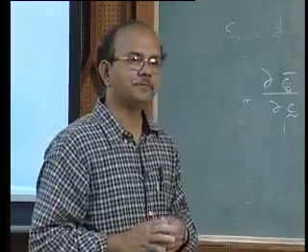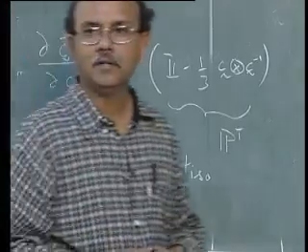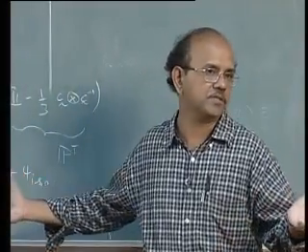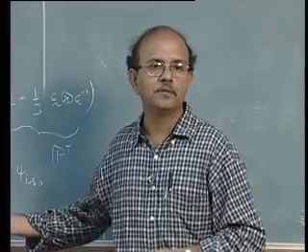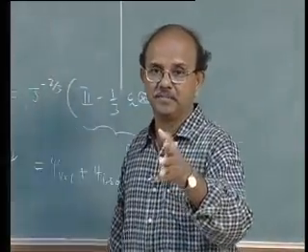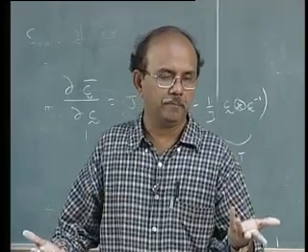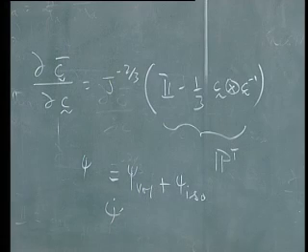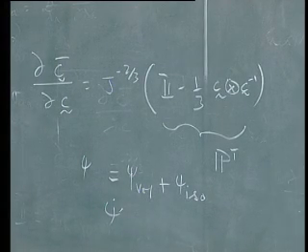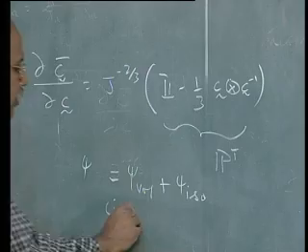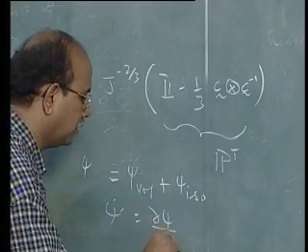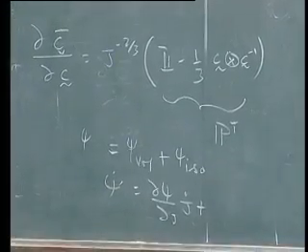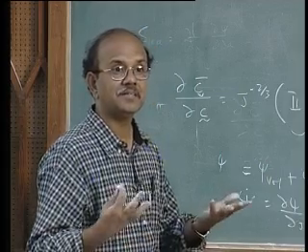Once I write like this, again see that we are going to use the old theory, what we know. What is it that I'm going to do now? Ultimately I want to develop a stress-strain relationship or stress-deformation relationship. All of them are elastic materials, so my choice is very simple. I find psi dot, where the volumetric part is a function of J dot, plus the isochoric part, which is written in terms of C bar.